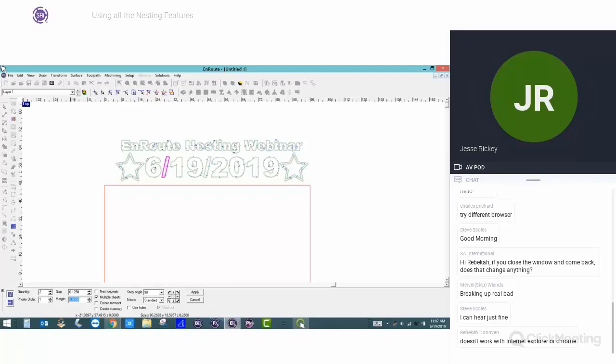So what I'm going to do is put a 1/4 inch on the edge of my sheet. So that's a 1/4 inch in X and a 1/4 inch in Y. It will leave that around the edge of the part. For instance, if I don't have a vacuum table, if I have clamps, I may have to put it in even farther depending on how many clamps I have in there, or if I screw down my part. So you can actually utilize this margin here to keep a clearance around the edge of your part.